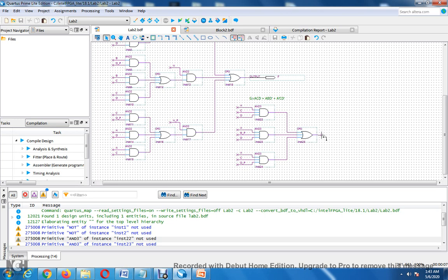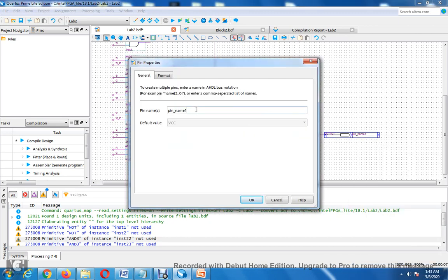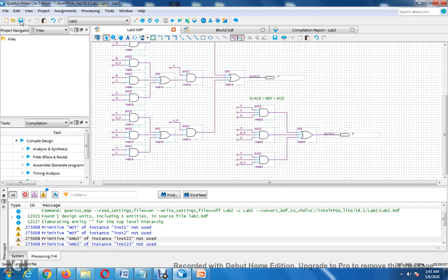I didn't put a G output on this one. I thought it was done. So go output, stick it on there. Then go escape. Escape is here. And then drag it out with the arrow key, and then label it F. So if you're not producing the output, a lot of stuff's going to be unused. And then save it. Okay, so now we'll just give it another shot.